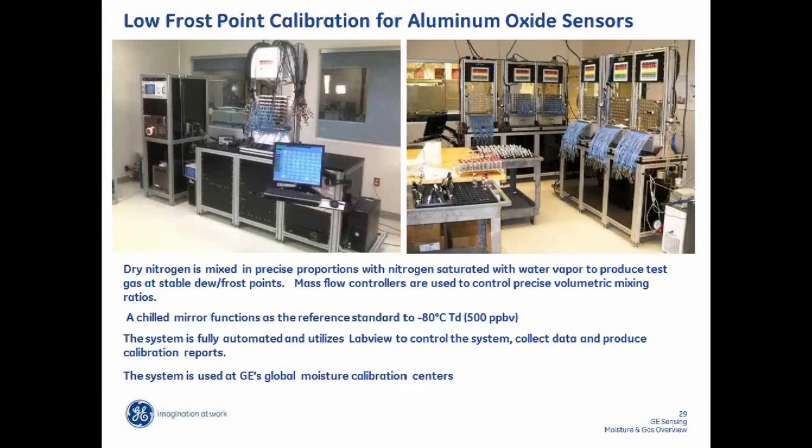And cleaning the mirror is a fairly simple process. You're just putting distilled water, or distilled water with a bit of methanol, on a cotton swab and swabbing the surface of the mirror while it's heated. So it becomes a routine thing for us on every calibration run. But it's overkill. We don't have to do it. We could probably not clean the mirror except maybe once a year, because our gases are very, very clean.